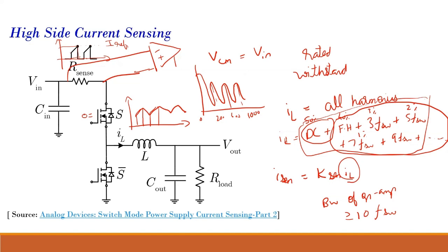And then when sir reduced the input voltage, what happened was the duty ratio, which was earlier less than 0.5, became greater than 0.5. Okay, and what happened was subharmonics came into the picture. At 100 there was a peak, and at 300 also there was a peak. These components got added because of that subharmonic instability. Okay, my diagram is not clear, but that's what sir showed.